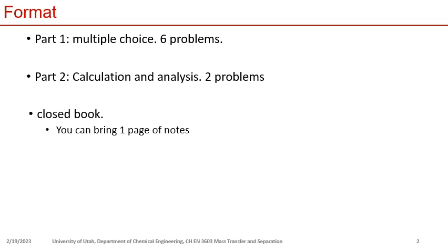Then how do we solve for x_A as a function of t, or C_A as a function of t? Similarly, how do you solve x_B as a function of t, C_B as a function of t? Okay. And how do you derive the flux of A in the tube, right? Under steady state assumption, we have proved that N_A is constant throughout the length of the tube, right? If this is z, this is z equals here.